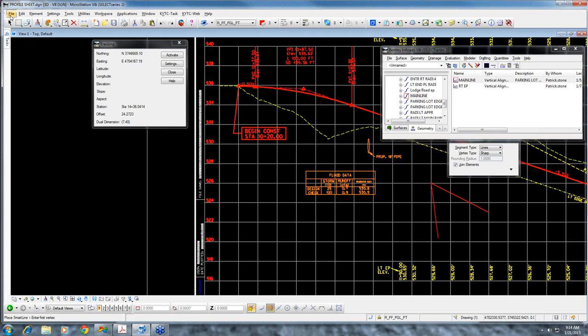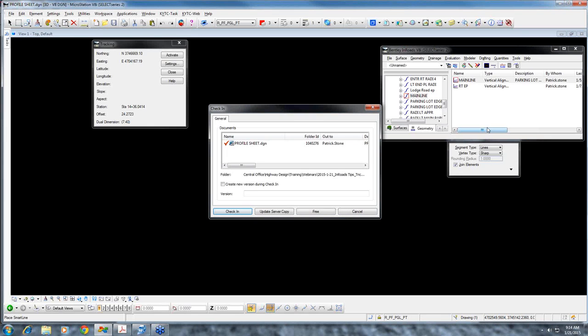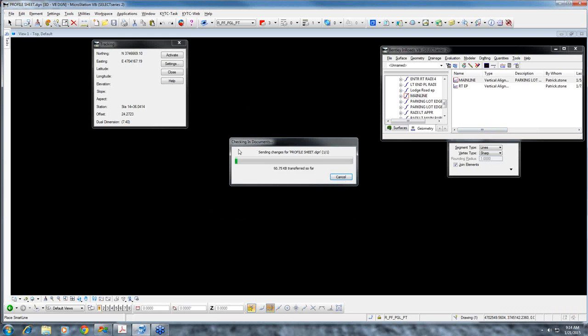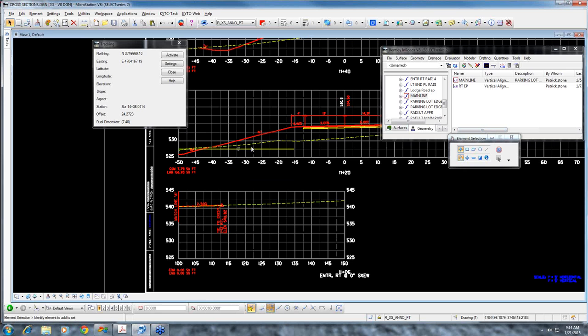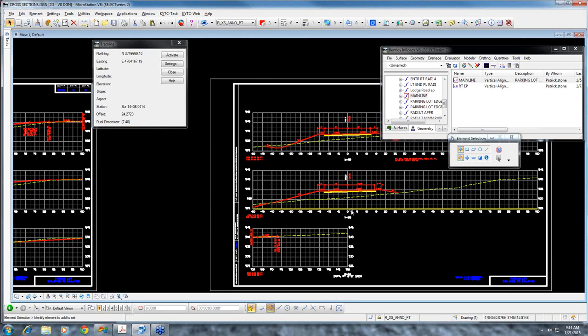Let's hop in the cross section here. Bear with me while I switch these files around. And all we're going to do on this is talk about how, like the distance grade, you probably use that for setting slopes for an entrance or the offset elevation. Maybe you're putting in a pipe, you want to dimension and show a pipe on your cross sections if you don't have it as a feature. And then the delta offsets work the same as in the profile.